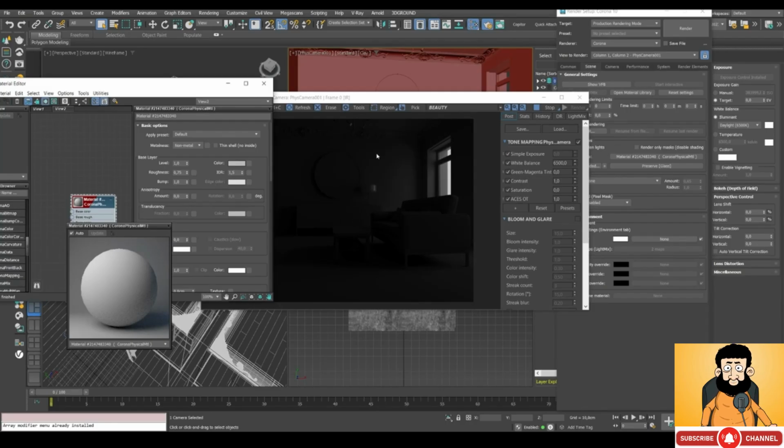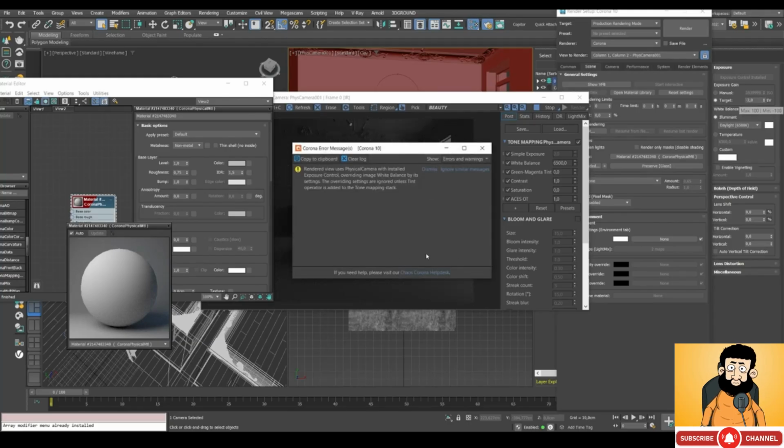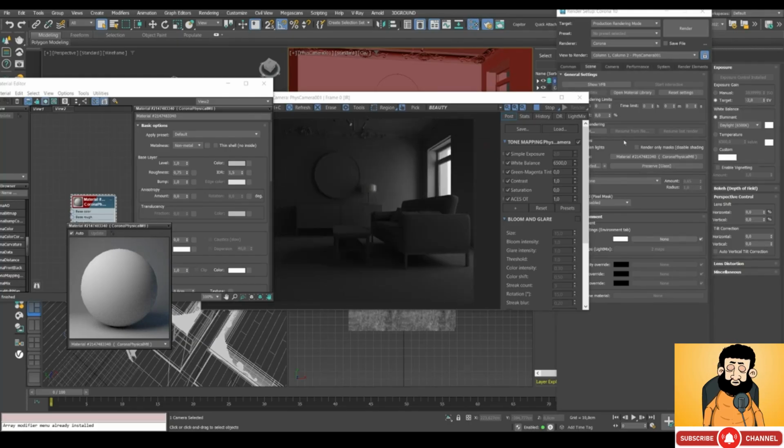We see that at the moment it's too dark. The material in our render should match the color of the sample as a general rule. And that's very simple. To achieve that, you simply need to adjust the exposure. And let's put it to -2. Or maybe -4 even.